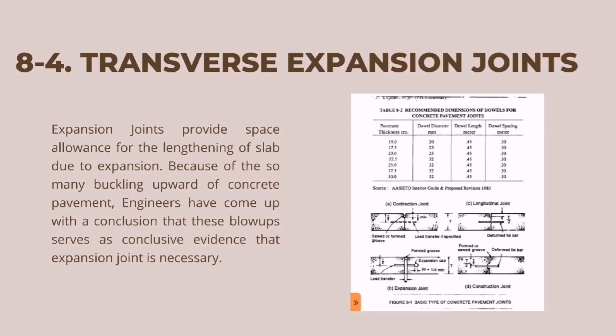A concrete expansion joint or control joint is a gap between two concrete slabs. It allows the concrete to move when it expands and contracts due to temperature changes. Control joints create a break between concrete slabs and the other rigid parts of a structure. They allow movement without causing stress, which helps prevent cracking.